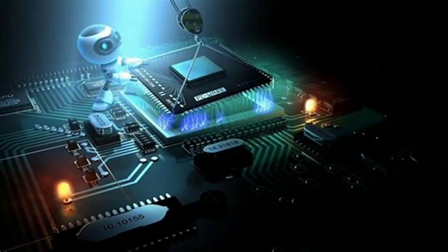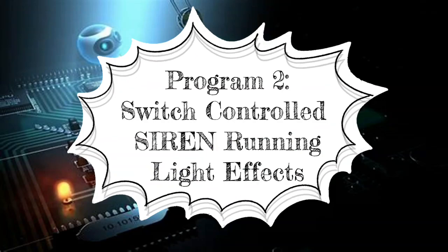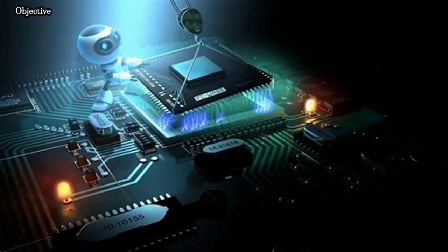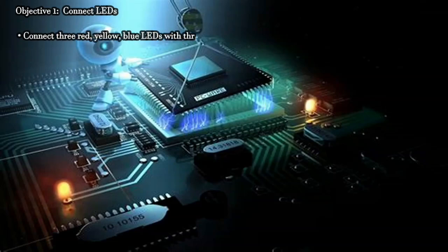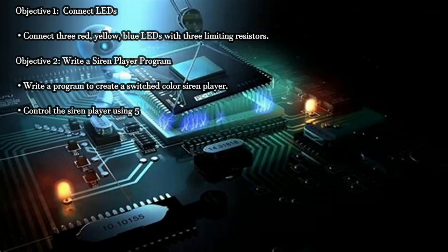So let's proceed to our program 4, the switch controlled siren running light effects. For this program, we need to connect 3 red color LEDs with 3 limiting resistors, another 3 yellow colored LEDs with 3 limiting resistors as well, and another 3 blue colored LEDs with 3 limiting resistors to our Arduino board via the breadboard.